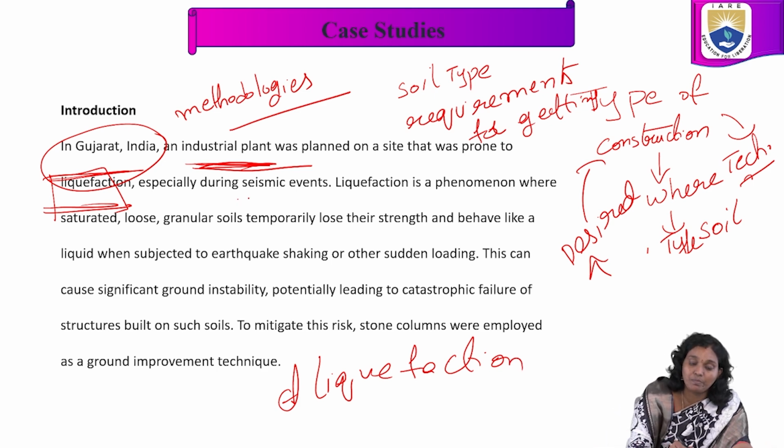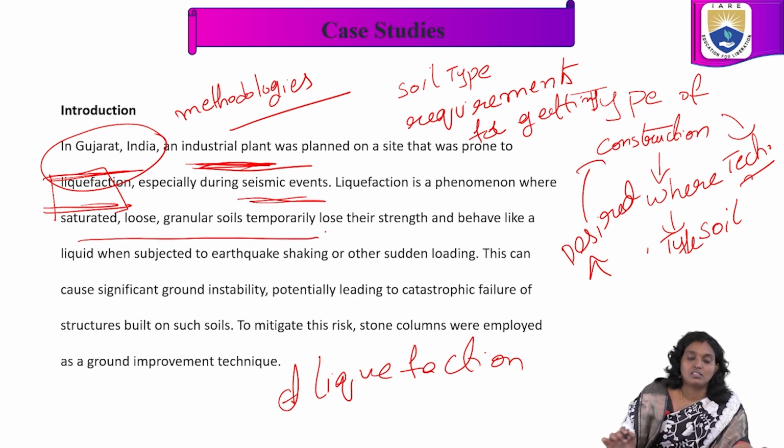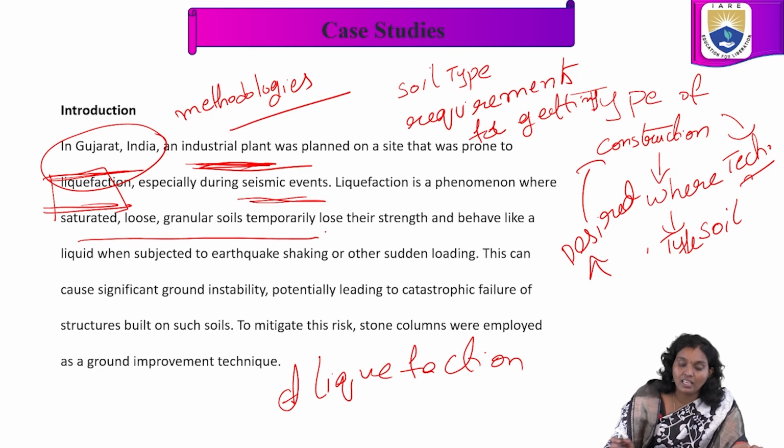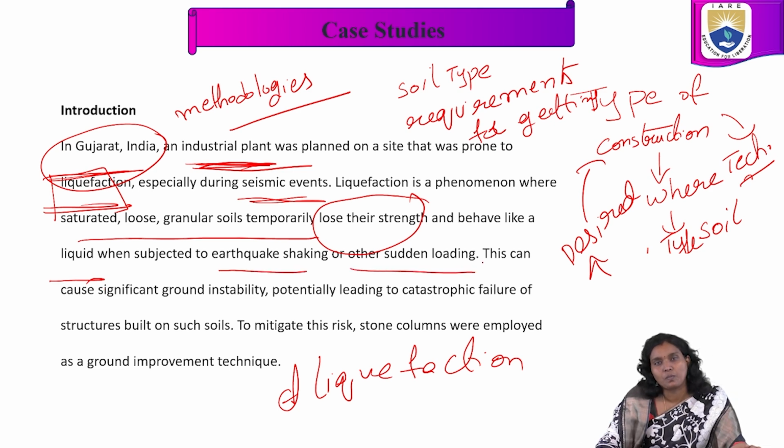Especially during seismic events, whenever there are earthquakes, liquefaction is a phenomenon where saturated, loose, granular soils temporarily lose their strength and behave like a liquid when subjected to earthquake shaking or sudden loading.